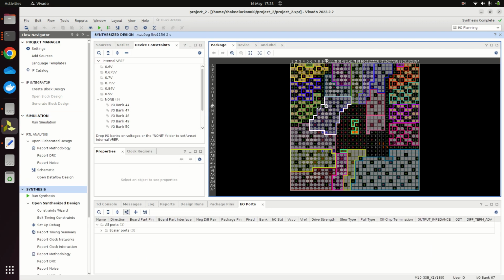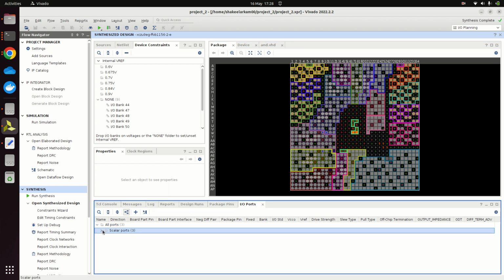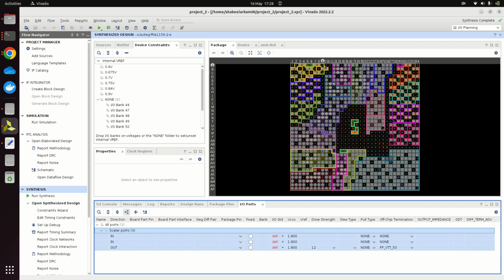Okay, so this is the design of the FPGA ZCU102. You can have the pin ports and the configuration for that. For example, we haven't given anything here. So now the exact hardware things come up, because these are the pins of the FPGA, which are basically labeled with rows and columns, that we have to go to and can assign to the specific thing.